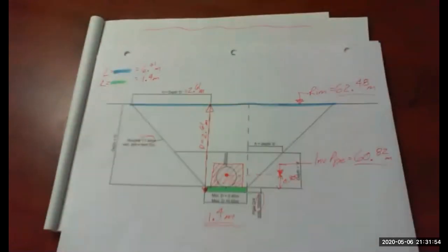That's a very small part of it. So you're calculating quantity takeoff. You're listing your work activities. You're costing your quantities based on productions that I give you. And then you come up with a final estimated cost for the question. So it's very similar to the example that we did today, and it's very similar to the assignment that you will do this week that I just posted to the Learning Hub.